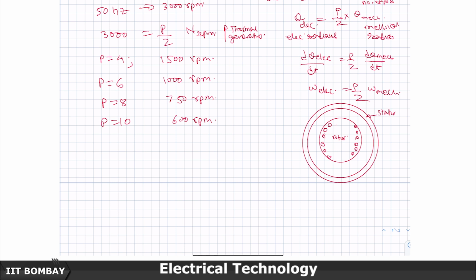Stator, this is north south. So, this will be dots, this will be crosses, cross means current is going inside, dot means current is coming out. So, if I run it like this, north to south, it moves in your direction. So, I get this as the north pole. So, the B lines will, sorry for my poor sketch, but the B lines will look like this. And then I have a winding, say, sitting here, and this north south is rotating.